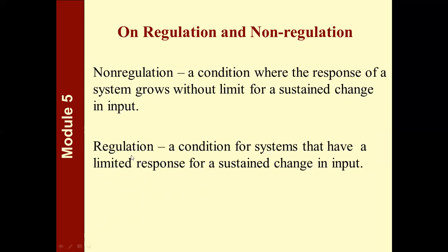The terms non-regulation and regulation. When you speak of non-regulation, this is a condition where the response of the system grows without limit. The response grows without limit for a sustained change in the input. On the other hand, regulation is a condition for systems that have a limited response for a sustained change in the input. A very simple example for this is the step input. So it's a regulated system if we have a step input. A non-regulated system is like a system which is subjected to a ramp input. Okay?